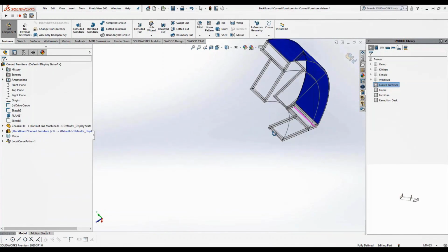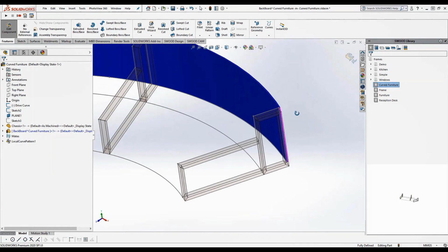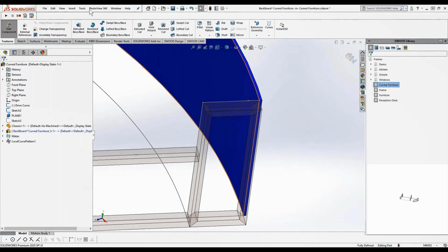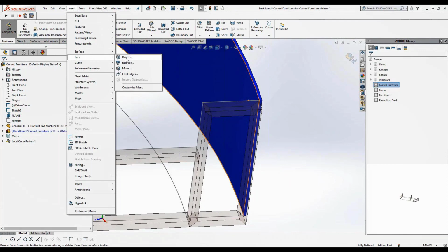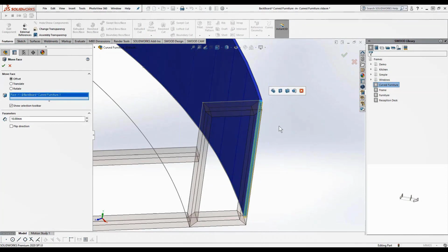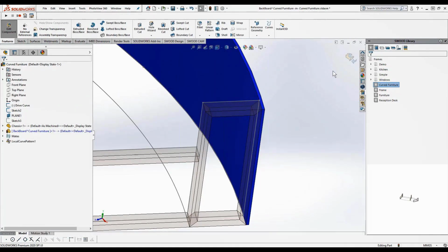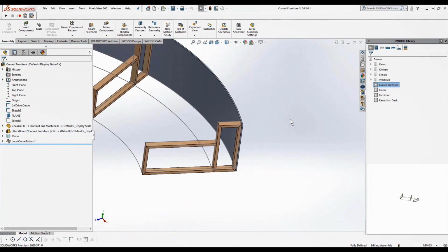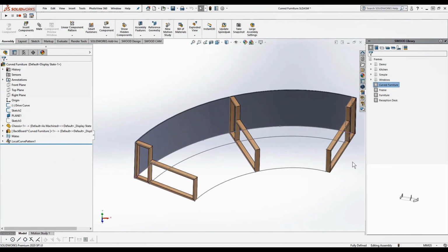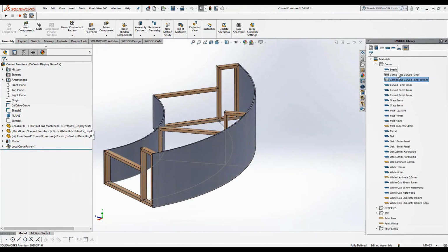Of course, anytime when you create your part, if you need to modify it, you can go back to the function to modify it, or you can just tell the system here, I can directly modify any face to extend the face, get some additional length. For example, here, just tell it I want 50 millimeter additional length to cover all my construction. And now the backboard is created. So exactly in the same way, I can create the front board, I can create the backboard. So the curved panel is created.